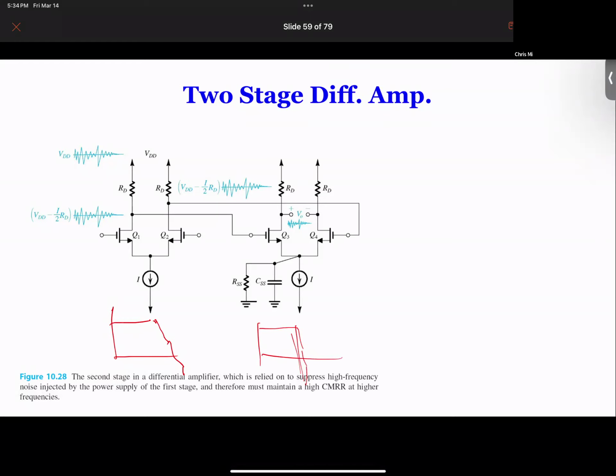So this is really bad, because your common mode rejection will drop so quickly that any signal falling here will be in trouble. Of course, when you design your circuit, you want to make sure your signal is in the middle band. But your circuit always comes with noise, and you don't know where the noise frequency is going to be. So it gets amplified for the common mode, and now you have trouble. That's why, when we design electronic circuits, there's so much trouble: I'm using only the middle band, so what happened with my signal? Something is not right. And that's because your common mode rejection ratio started to decrease dramatically.